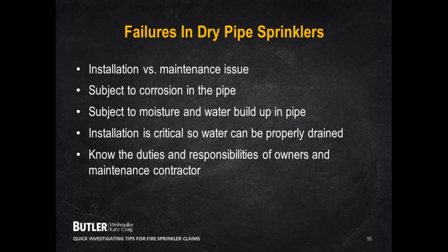No, let me take that back. A certified service contractor has to conduct the flow test. The owner has to maintain the system at all times. A lot of times your owners of the building, your insureds, they will hire service maintenance contractors. But at the time that the maintenance comes around, the pipes have to be constantly checked to make sure that they are dry, because condensation will build up and condensation has to be drained off the dry pipes on a regular basis. And that is the duty and the responsibility of the insured.